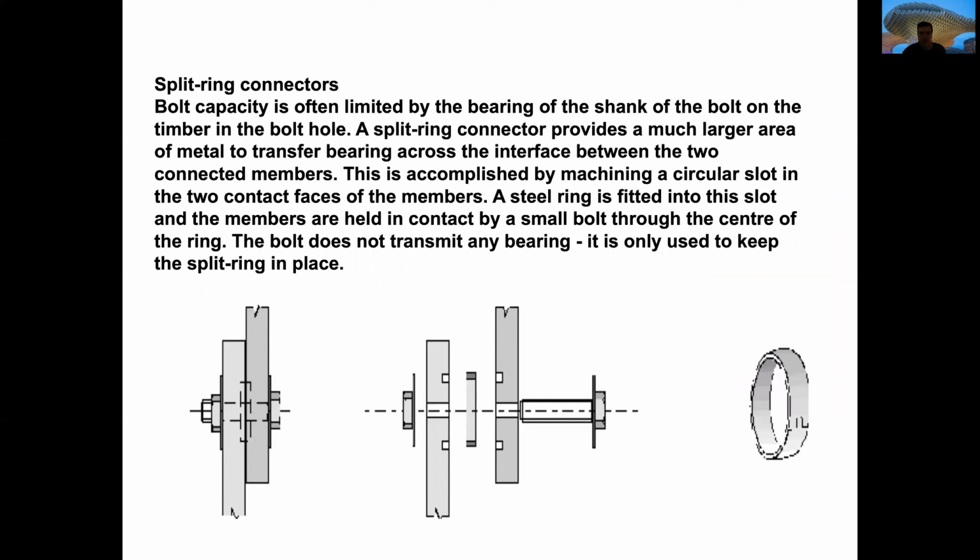One of the inconveniences when we're speaking about bolts, and you will see when we do the calculations, we will do calculations of bolts when we speak about steel, is that the resistance of this type of connection depends on the thickness of the bolt, and the bolt cannot be so thick because you are also making a hole in the material.